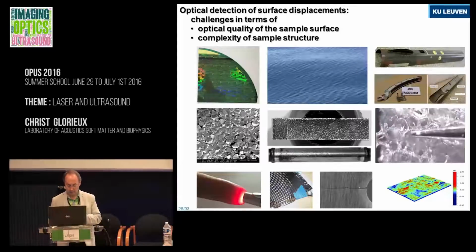Components used in this, this is from a helicopter. This is the slat rack, from an airplane, to bring the wing out. This is a bit magnified. This is nanocrystalline diamond, a very thin layer, 800 nanometers. This is a sample, a protected steel fuel cladding from a nuclear power station. So you see it's very rough, but people want to know the elastic properties because they say something about the quality of the sample. The stiffness depends on the structure, so it's a useful quality, and also the thermal diffusivity depends on the structure. So they are useful things to measure.